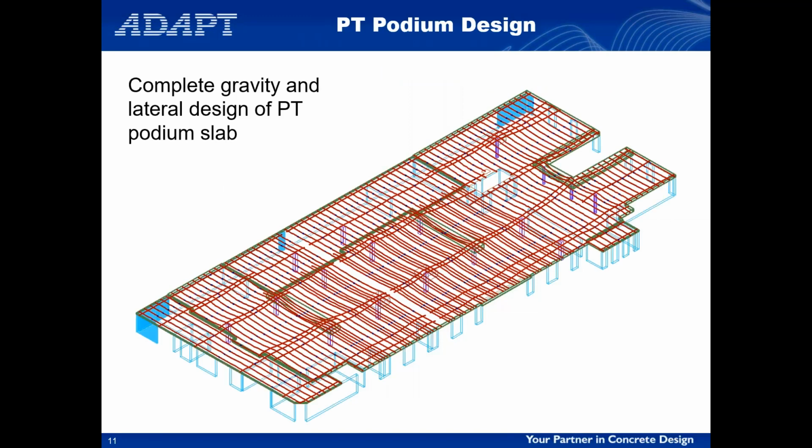Once we have our loads defined on the podium, the design of the podium itself is no different than any Floor Pro analysis and design that you've gone through. You're just running it in single level mode, laying out your post-tensioning, laying out your support lines and everything else. One question does come up, and this just crossed my mind. It's not in the slides, but I think it warrants raising.